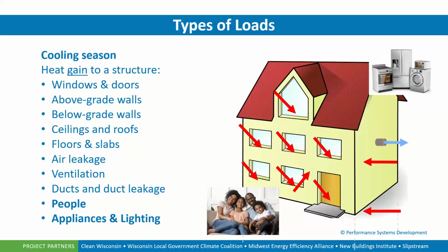And it's important when we start to list all of these items, whether it's a heat loss or a heat gain, that it can be accounted for within the Manual J and overcome. And sometimes it's not a huge gain on the BTU offset, but occasionally it might be a rather large gain. So we may find out that a track builder, this size home, based on heating and cooling gains, and historically they put the 3-ton HVAC system in, say heat pump, and then when they run the Manual J, they find out they maybe need 3.5 tons for this house.